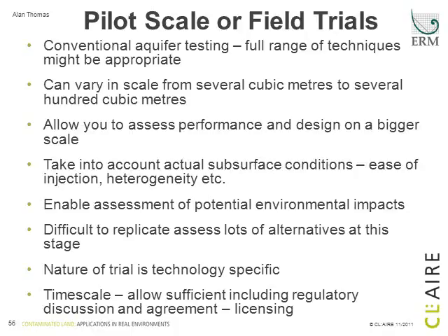Pilot scale or field trials are commonly used in in situ bioremediation design. Initially we may undertake conventional aquifer testing, but more realistically we'll also undertake a specific trial focused on the technology of concern. This can vary in scale from several cubic meters to several hundred cubic meters, and it's really allowing us to assess performance, design and delivery on a bigger scale, and, as I've said, taking into account actual subsurface conditions, things like ease of injection, delivery through the heterogeneity, etc.